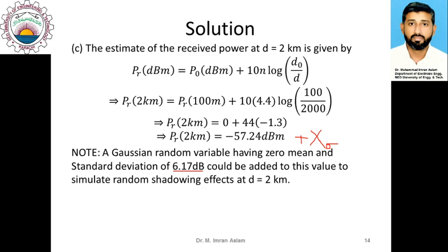So this was our problem, and in this problem I tried to explain how we can calculate the path loss index for this log distance model if we have some measurement values, and this is a very common technique used to calculate the path loss index values for different types of environment.